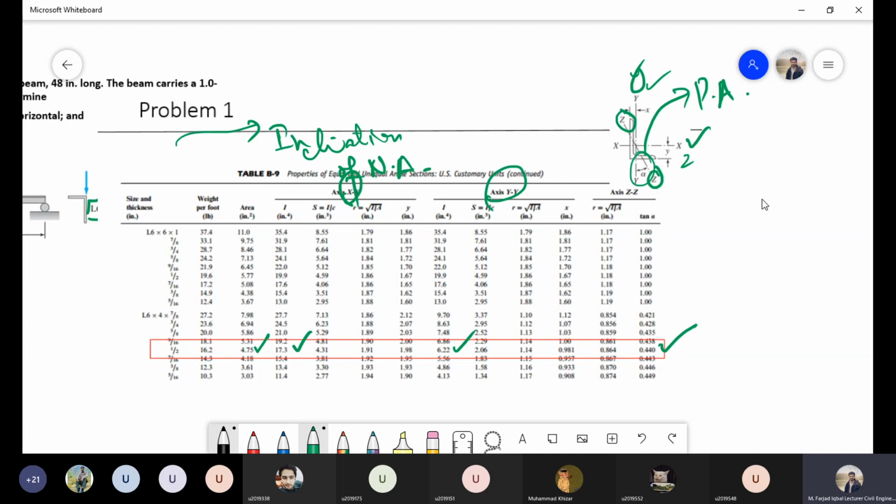and it has provided me with another term, that is the radius of gyration. Okay, now using this radius of gyration, I can calculate the moment of inertia of this particular section or of this inclined principal axis. So because I know the area is 4.75, the radius it has provided me as 0.864, and I will simply substitute it back into my equation of R, and I can calculate what my I for the principal axis is. Now, any question about this one?